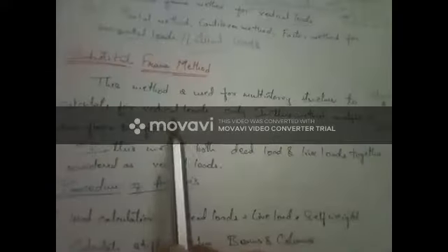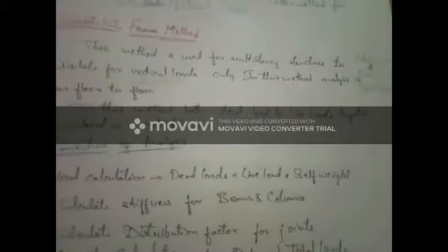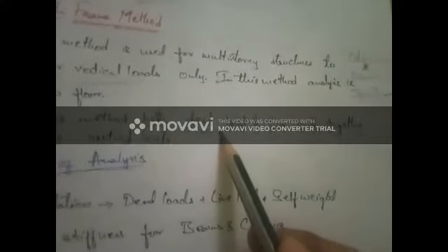And when you go for analysis, as we have discussed, it is only for vertical loads. Those vertical loads are dead load, live load, and in addition to the dead load we have self weight as well. Here dead load is similar to the self weight, but additional to the existing self weight there are some dead loads that we are also supposed to add to this frame.